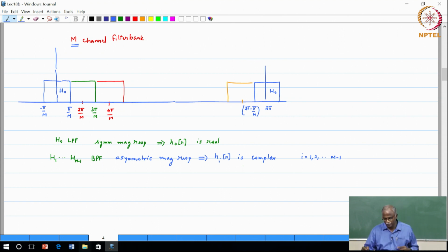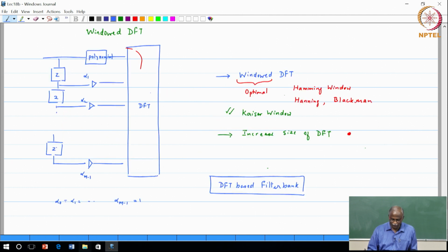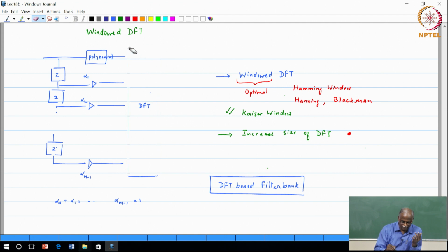And you go back a full cycle and say, if you want a very good spectral analysis, then design a very good filter. Of course, use the DFT or IDFT, whichever one you want, both of them are equivalent. And once you have that as your underlying framework, then your ability to work with spectral analysis significantly improves.